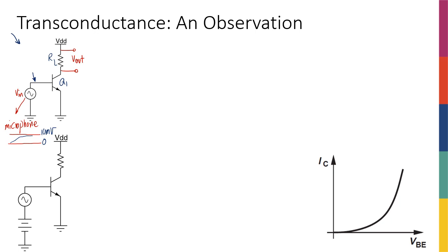And I've decided that this 10 millivolts maximum is not enough for me. I want the maximum to be 100 millivolts, meaning that I want to amplify this signal. Therefore, I would like my V out to be between 0 and 100 millivolts, right? So I want the gain of this transistor to be 10.